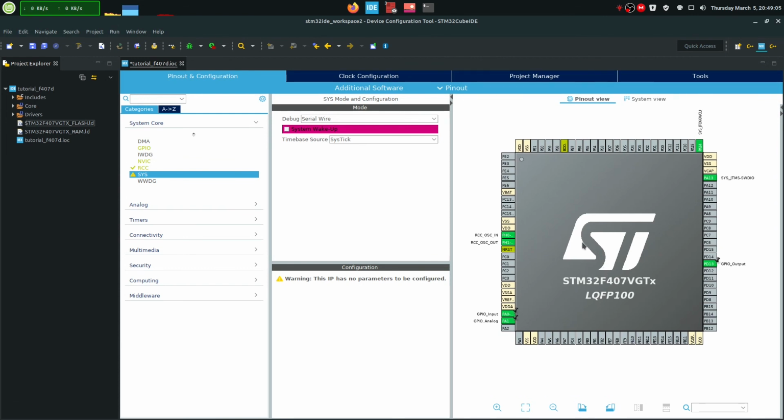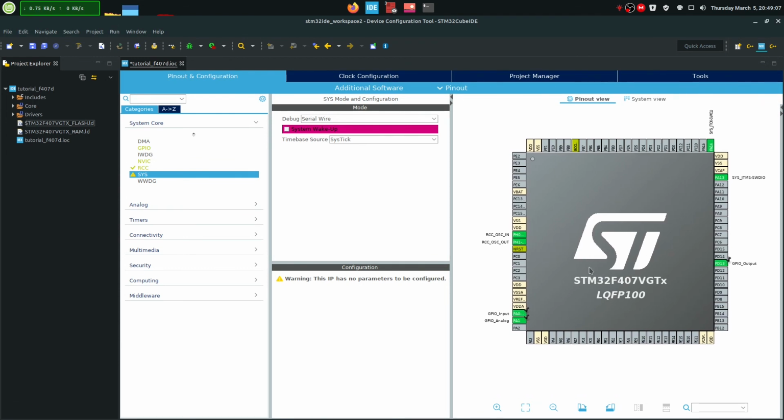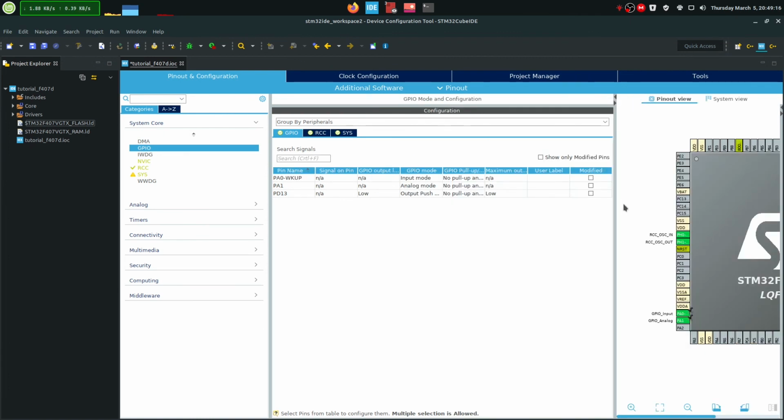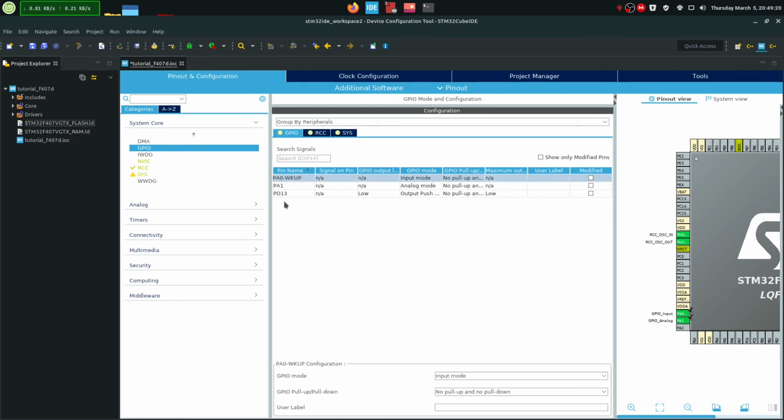So we have initialized our pins. We told the software which we're gonna use, but we also have settings for them. We talked about them before. And we can do that by going to the GPIO portion, and here are all the pins. Let's just widen this up a bit. We don't need the processor right now anymore. And let's go to the PA0.